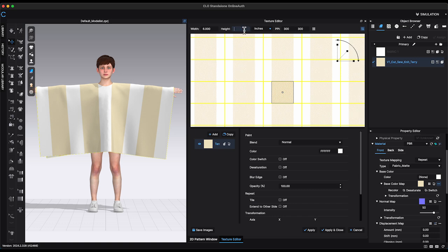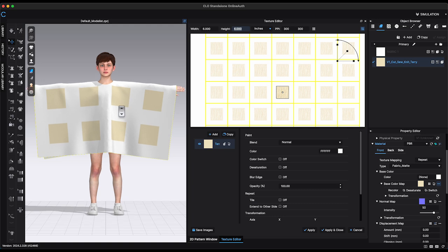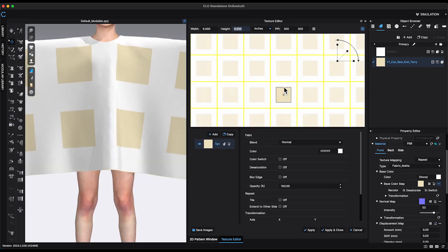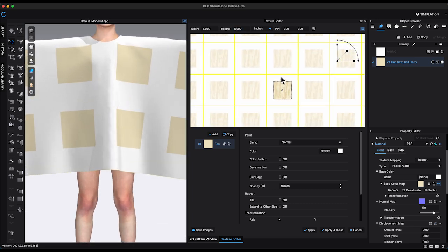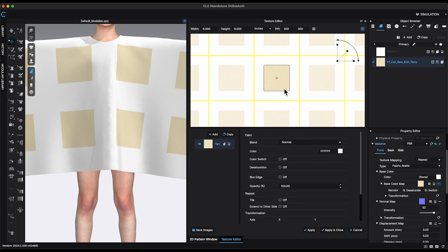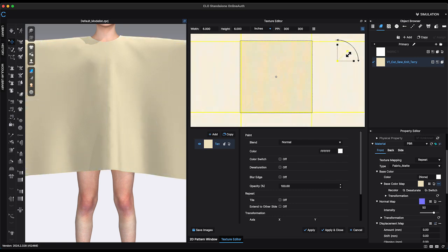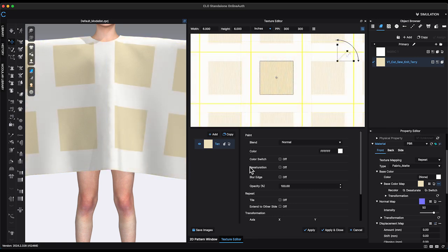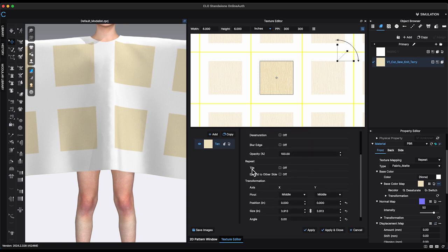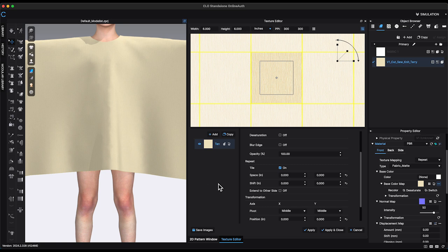After enlarging the square, the original texture fabric stayed the same, which caused the texture to not fill the space. To fix the issue, you can use the texture wheel to adjust it. However, this will also scale up the texture, which may not be ideal. To avoid this, turn on Tile function from the lower window section, and it will fill up the square automatically.